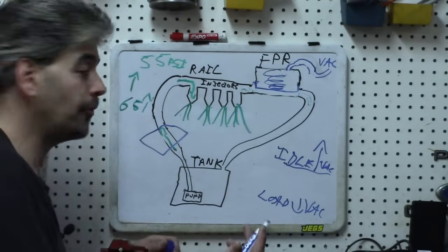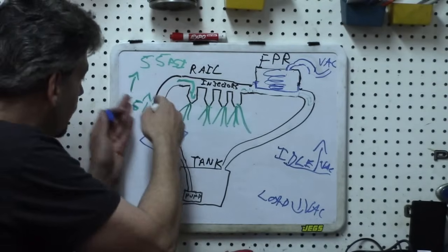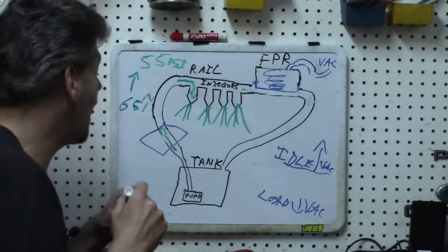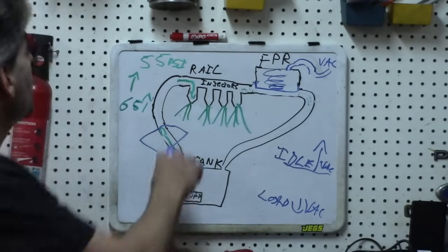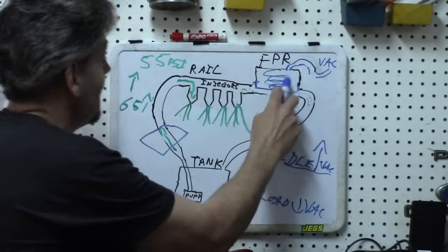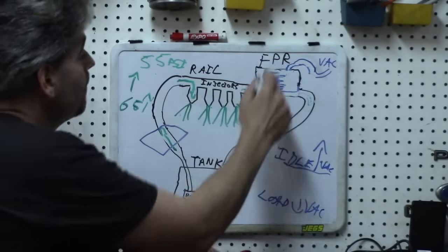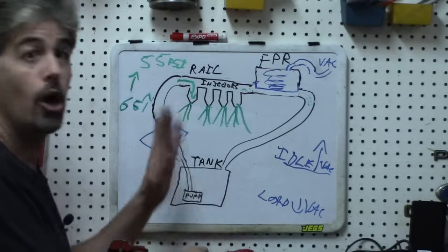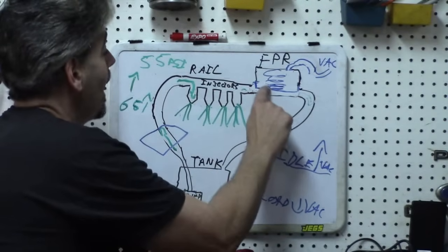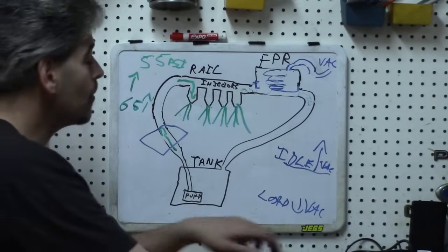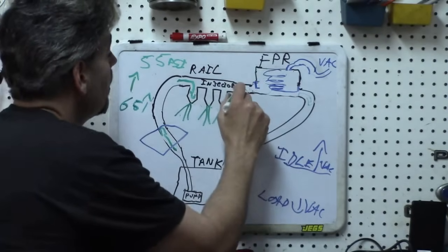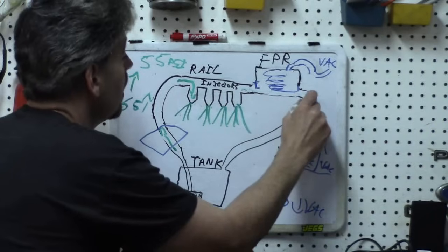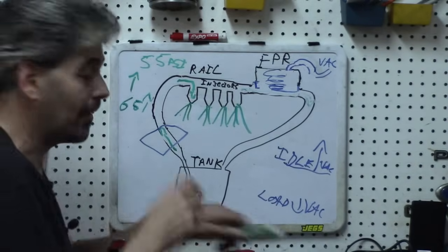What if the fuel filter is clogged? What if there is some type of restriction in the fuel lines? It could also be the fuel pump itself is bad, of course. But another possibility could be, what if this spring is broken? Or what if the diaphragm has a leak? Either of those situations would cause this fuel flow to the return to always be very high.